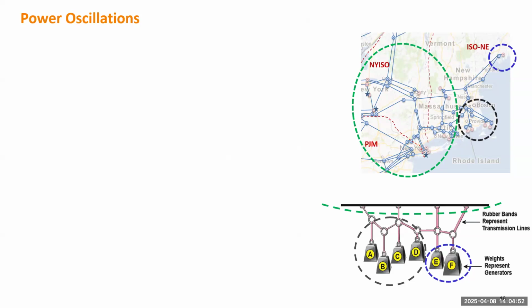All right, next we'll move to more general cases, a power system with many generators. We definitely can borrow a similar analogy with a harmonic oscillator, but for a more general power system with many machines, sometimes it's hard to say which machine can be considered as a harmonic oscillator. The oscillation will involve a lot of generators, but we still can somehow borrow some analogy from this mechanical system.